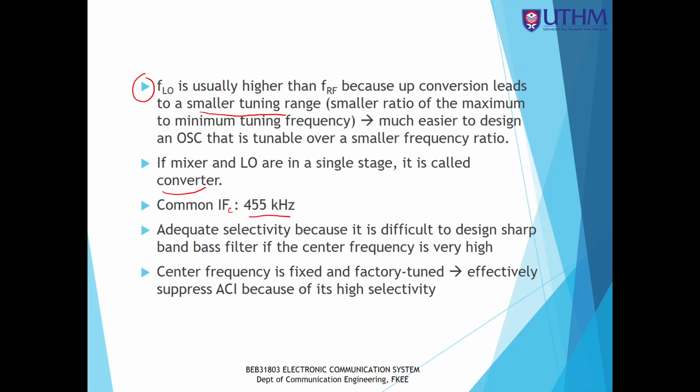This 455 is a standard value, selected so that we can have adequate selectivity to design a sharp bandpass filter in the IF section later.